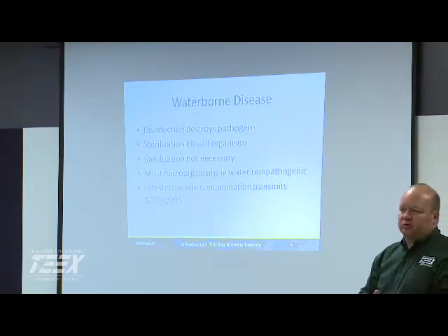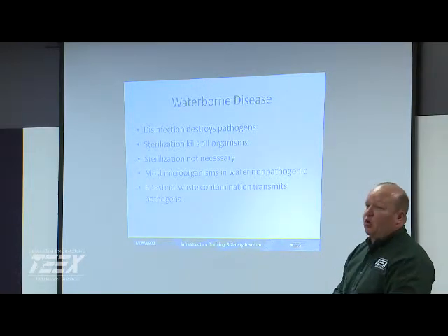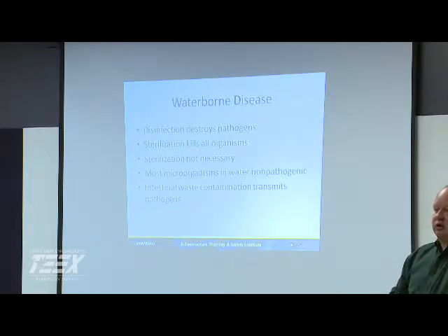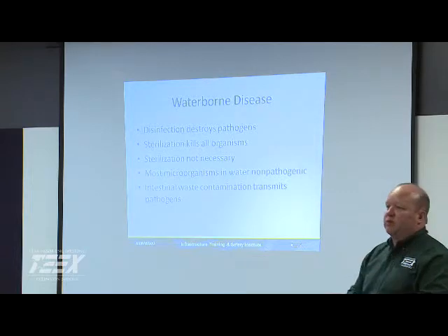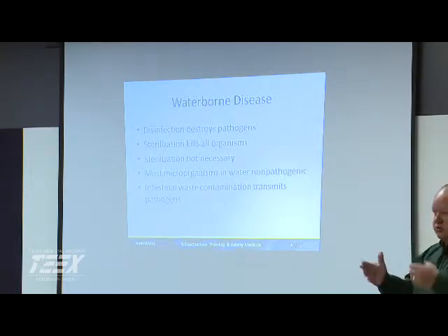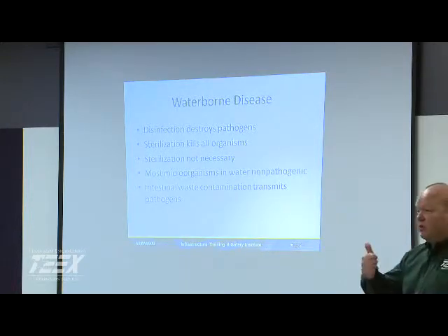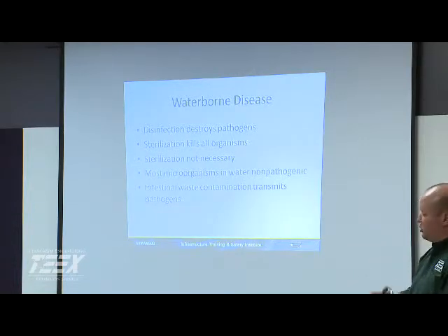As we know, Crypto and Giardia aren't inactivated by chlorine, so we need to use other techniques. And so they're sending that off, and wound up having over 100,000 sick, and a number of people died because they didn't recognize the problems with the process. And so part of the Safe Drinking Water Act, one of the big ones was operator certification. And so training and competency is really important.